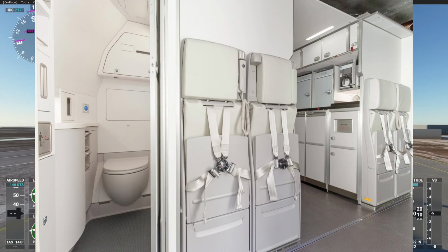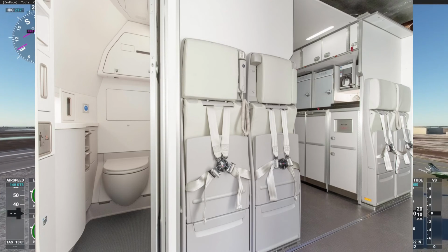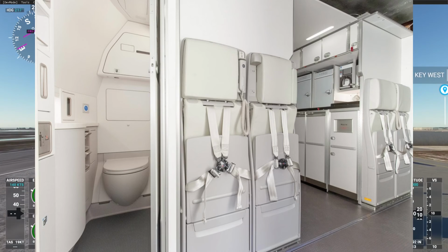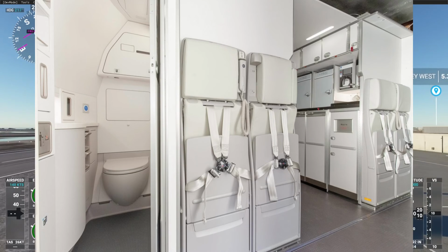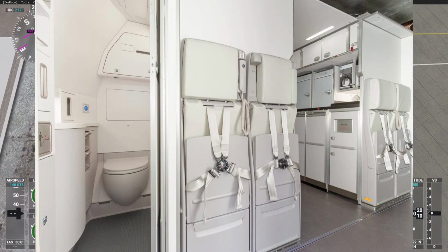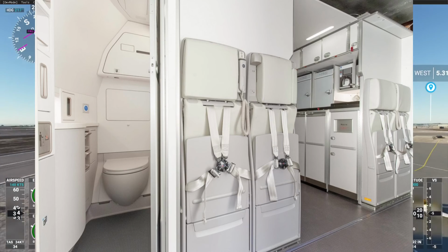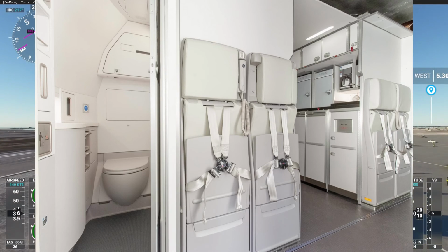And then we finally got the galley and lavatory ventilation. So this basically just makes sure that the air in the galley and the lavatories, you don't want that pooey air getting into the mixer unit. It's not healthy. So what we do is we extract the air from the lavatories and the galleys, there's some fire and smoke detectors that are in their system at that point, but then basically it takes it all the way to just about near the outflow valve and then vents it overboard with a fan, so that makes sure it doesn't go back into the cabin.